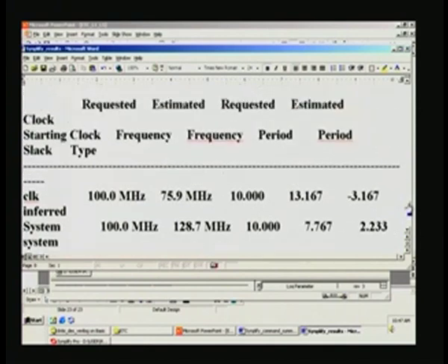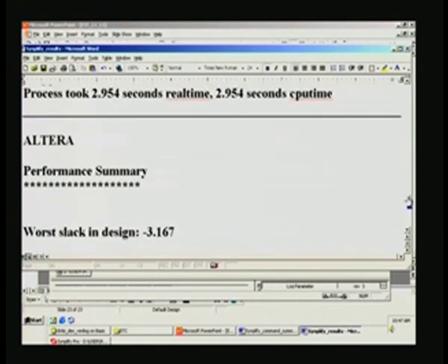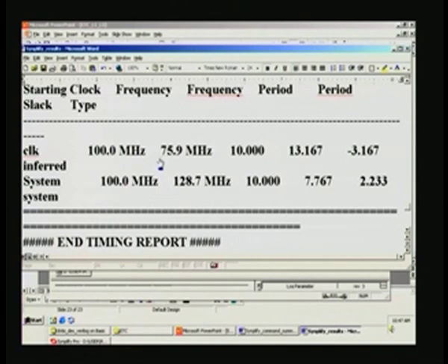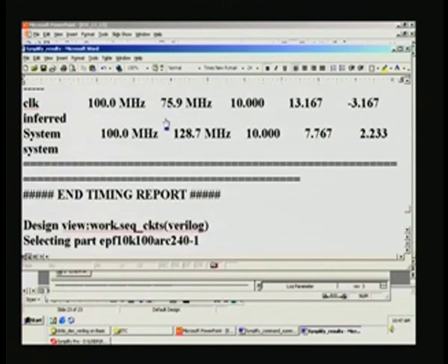And this one is, we want to compare with another vendor, say we are comparing with Altera, whose capacity is more or less same. So this is 100 ACEX, and in this case you get a lower speed, right. I may not be fully justified in making a one-to-one comparison without really seeing the actual speed the vendor has claimed. So the best way is look into the vendor specification and see what their claim is, and then make a comparison, and then choose the right device. And anyway I think I had taken the highest speed available in this category.